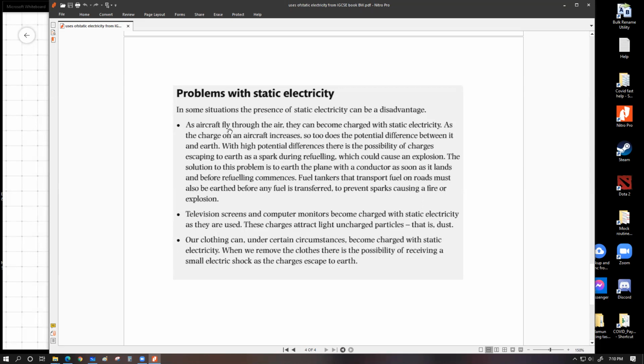And many of the fuels, for example petrol and anything higher in octane as well, are also volatile. Volatile means that if you have some open liquid fuel, visible liquid fuel, it will naturally evaporate at a really fast rate and produce a fuel-air mixture on top of the fuel, which you cannot see. So even a slight bit of a hot object entering this can make those things reach their ignition point, which we talked about in our thermal class, and start a fire, which will lead to subsequent firing of the neighboring molecules. All of this will work like a domino effect or a cascading effect, and eventually you can have a large fire, which in other words can be called an explosion.